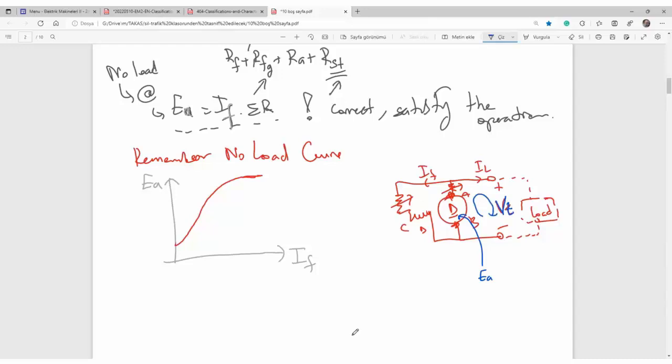And here is such a Kirchhoff's voltage law. When there is a reasonable, let's say 110 volt, output voltage, here must be a reasonable voltage. Because we induce electromotive force here, and then we deliver electric power and voltage up to here. That is the point where we induce electromotive force, which is the armature.